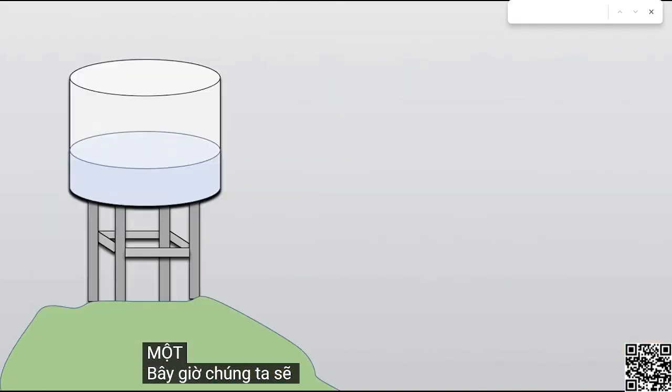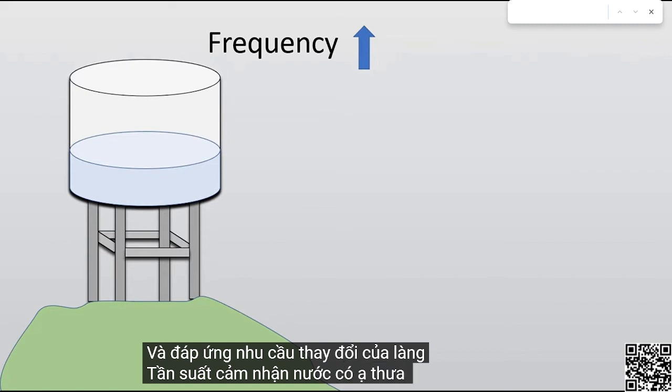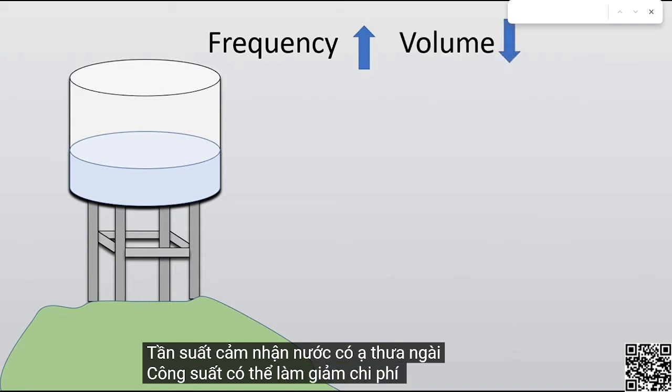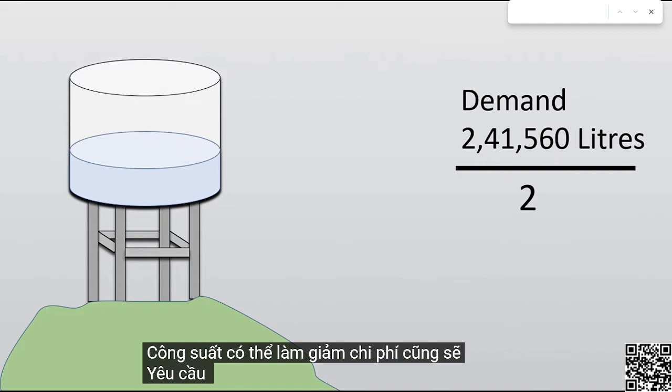Now, we will find out the volume of the ESR. This ESR should fulfill the demand of the village for a day. If we change the frequency of water filling in the ESR, then the ESR capacity can be designed for half or one third of the demand. So, it will reduce the volume of ESR needed and the ESR cost will also reduce. If the demand is 2,41,560 liters and we assume filling of the ESR 2 times in a day, then the ESR volume will be 1,20,780 liters.